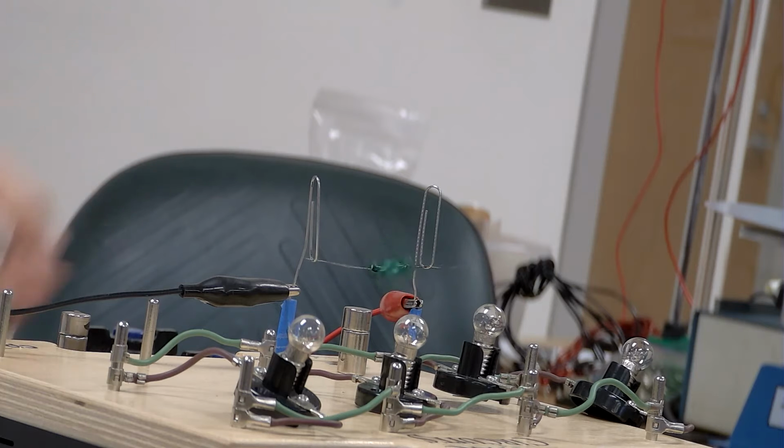And if it stops and you run current through it, then it's a short circuit, because all the energy is being converted to heat, right? And that's why this started smoking yesterday when I was playing with it in one of my other classes. Smoking's bad. But if it's rotating, then a lot of that energy goes to rotational kinetic energy. And so you don't have a short circuit anymore because it's not all being converted straight to heat. Okay?